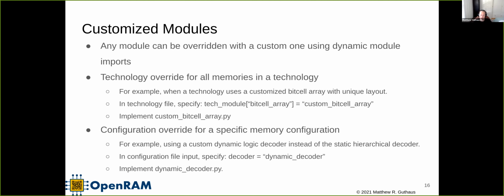But yeah, for the supply routing there's a number of options. Another thing that was challenging with the OpenLane OpenROAD flow is that the power supply router in that tool is very limited. Basically, you have to have power stripes to connect to their power routing. We used to have a gridded power router where we would just put a grid over it and connect everything to the grid, and a lot of the commercial tools would hook up to that fine. But in the OpenLane OpenROAD flow, we basically had to add a power ring around it, and it can only connect to the power ring.